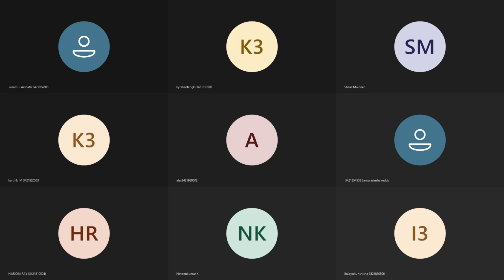So what are the types? Okay, so those are all the things we have seen already. Okay, so we come by categories. First of all, why do we have to go for the retaining wall? The retaining wall is to withstand the backfill soil which is there in the hilly regions, not only in the hilly regions, in the abutments of the bridge construction. Abutment is the end portions of the bridge. For the construction and design of that abutment, a structural element, we utilize the retaining wall.